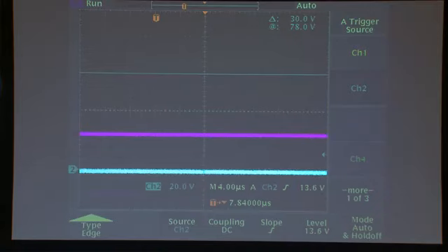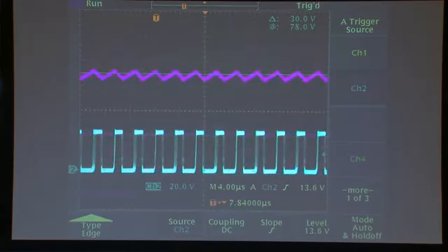Okay? So here we go. Let me power up the converter. And that's pretty nice, right? I get more or less periodic steady state operation. There's actually a tiny bit of jitter in the duty ratio here, but it's basically switching once per cycle and nicely settled down. What happens if I turn off the compensating ramp?